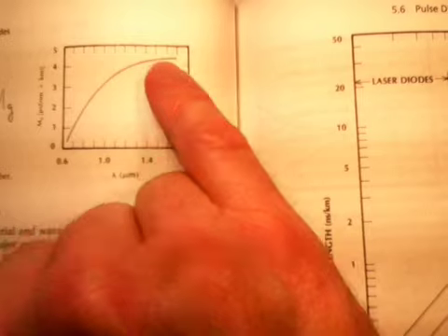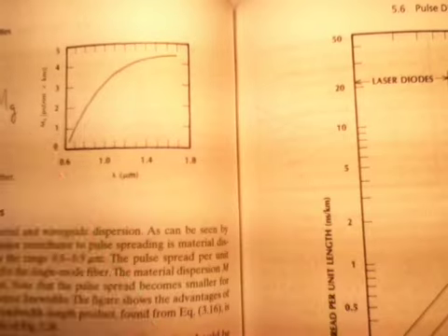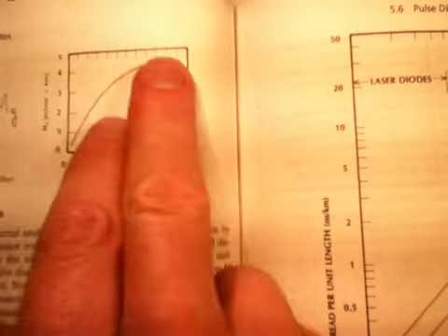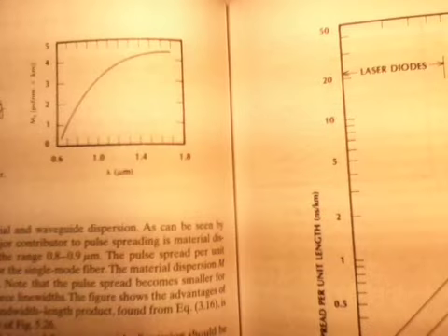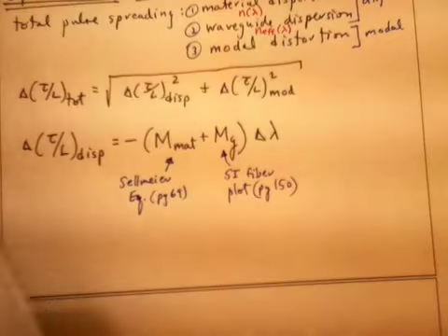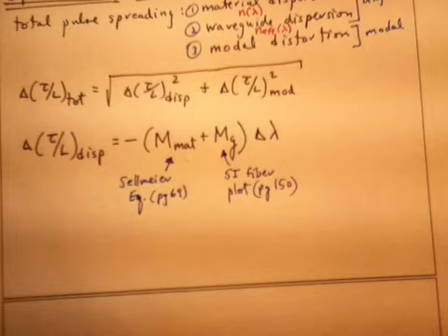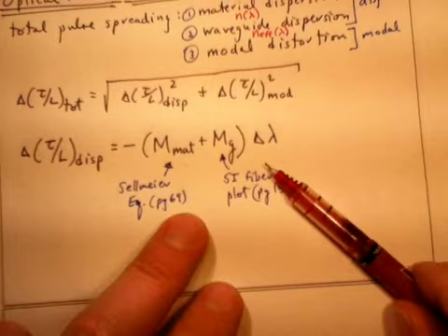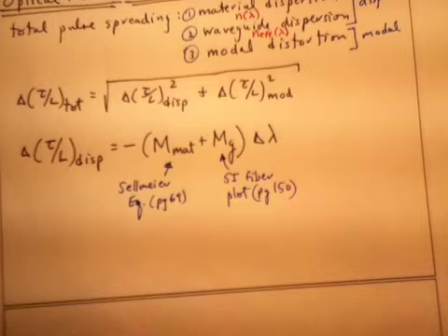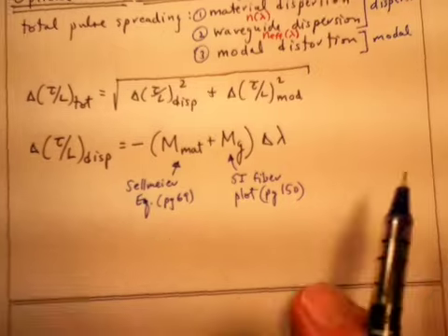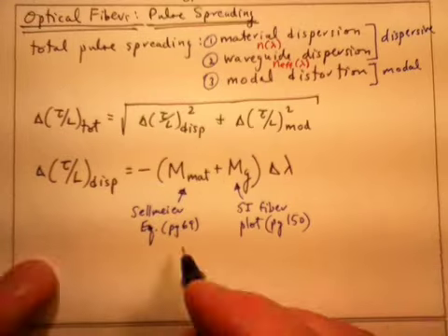And so the waveguide dispersion tends to shift the zero dispersion point a little bit further up from 1300 nanometers when we have a real optical fiber. Okay, a couple of equations that we can write down to further this picture and to give you the total picture is that